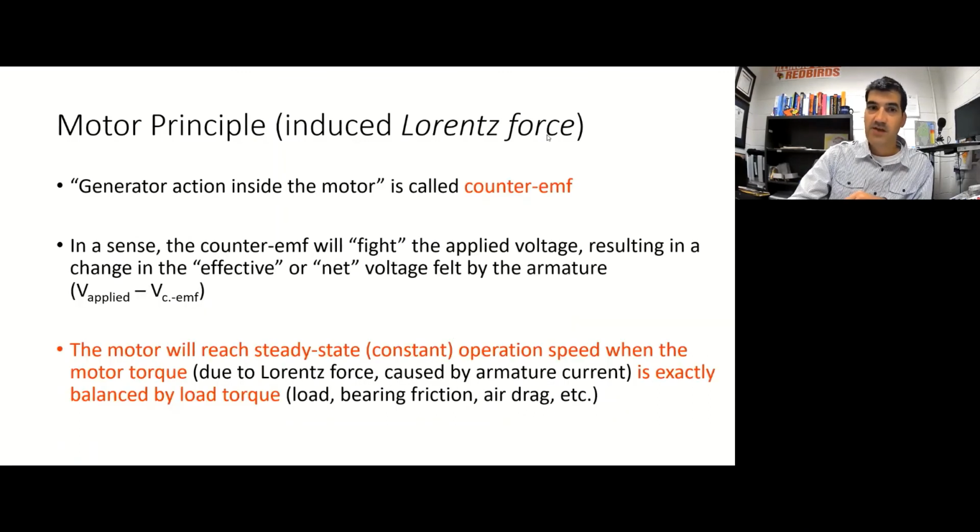All right, so that generator action inside the motor, we call that counter EMF. And these two things are fighting. The applied voltage and the counter EMF are fighting. And so what the armature really feels is the difference between the two. The voltage the armature is feeling is the applied voltage minus the counter EMF.